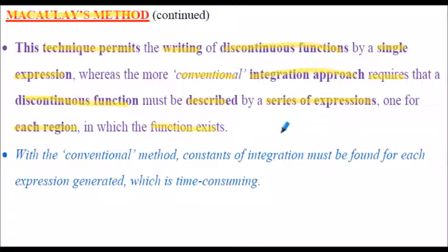So in our context, that would mean a different region of the beam where we have different applied loading. With the conventional method, constants of integration must be found for each of the expressions generated, and this is particularly time consuming. So using a step function simplifies the integration process, but we do need to adhere to the particular rules around the application of step functions.